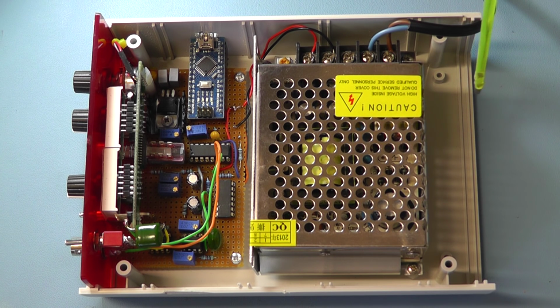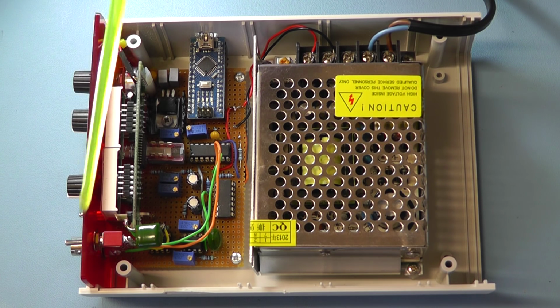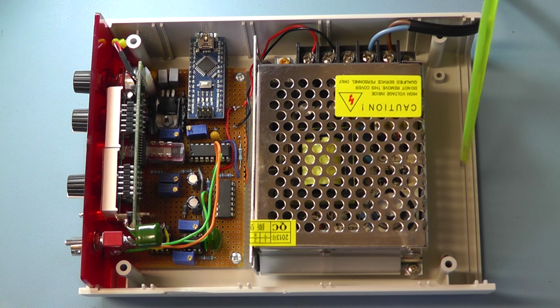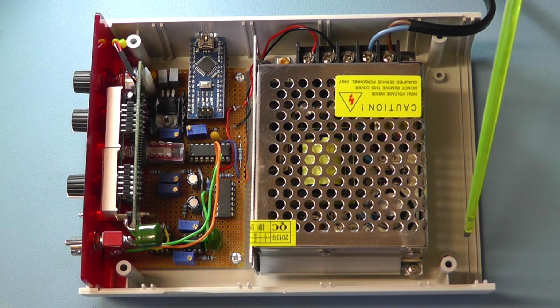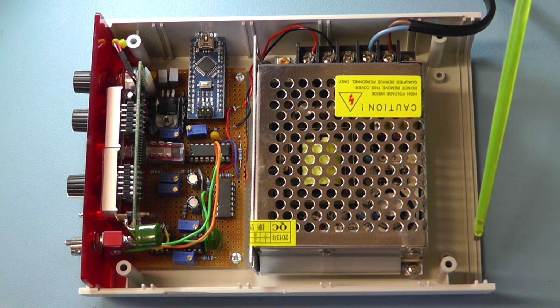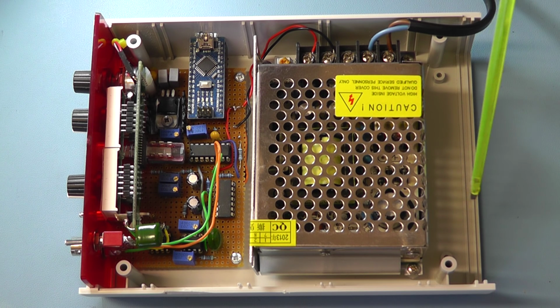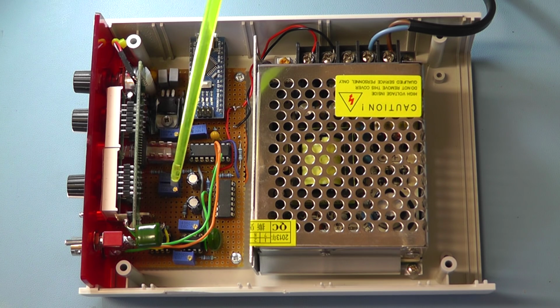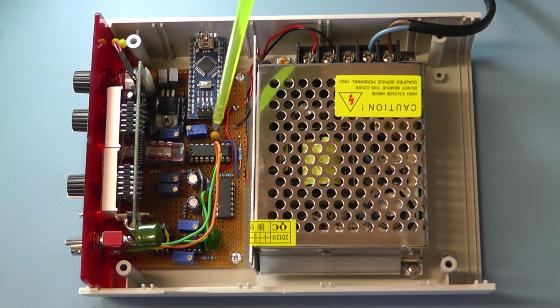Now the other options that we have with this, if you remember, is we have a pulse mode option, and there wasn't sufficient space on the front panel to put the control and the switch for that, but that could be fitted on the rear panel here, and you could also add on the rear a TTL output, square wave TTL output, with a second BNC socket on the back. And for those that were wanting to use this also as a standalone frequency counter, we can add another switch if you wanted to switch the function of the internal frequency counter to use as an external frequency counter with the BNC socket.